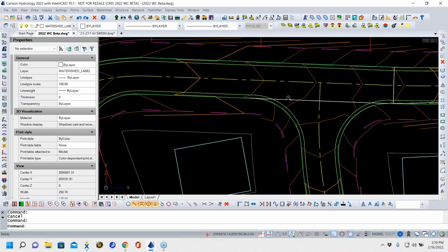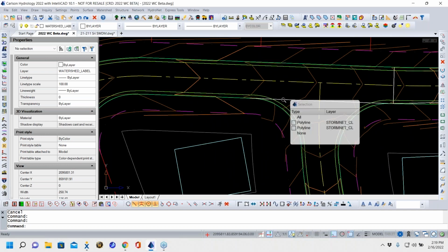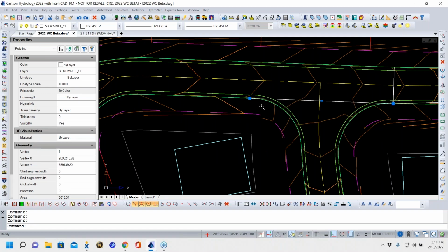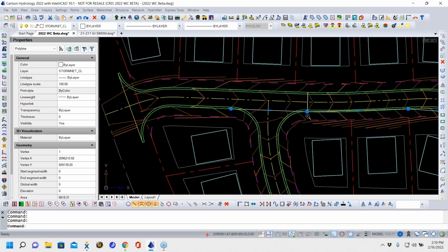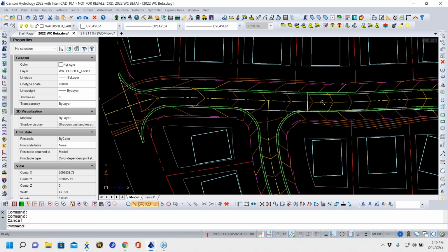Now for me, in Mark's world here, you can see that when I pick these two polylines, my PC is about right here. So my catch basin is 2.5 feet back from my PC. And that's why I put these in here so that I can have a point of reference and can snap. That's the only reason. It's just like a little guide of what I think I'm going to have to do.